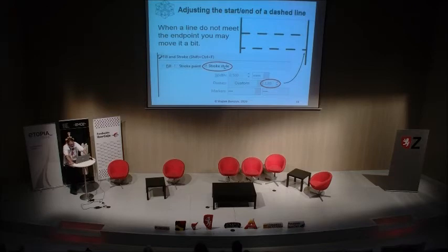And for this, in the stroke style, we can slightly move dashed line with this window marked, and we can move line to the left and have nice starting and ending dash which meet the lines on both sides.